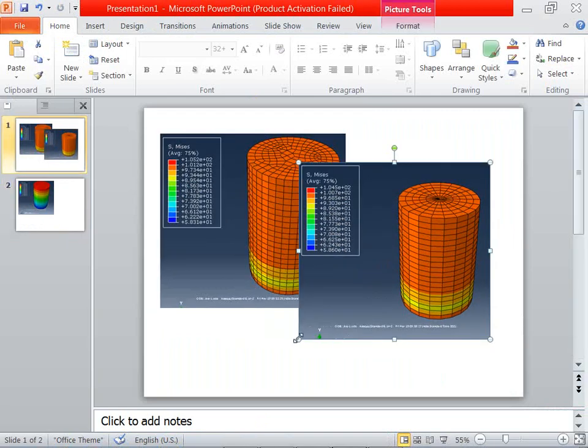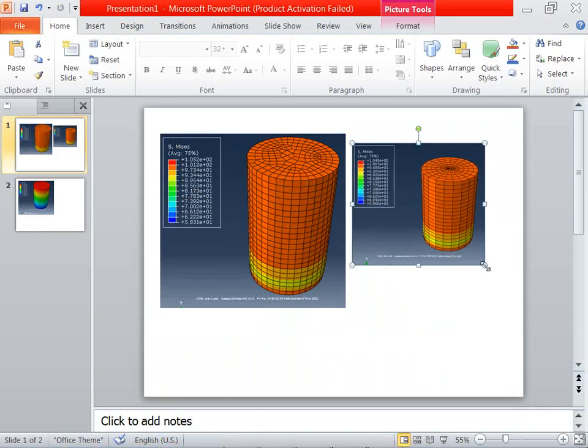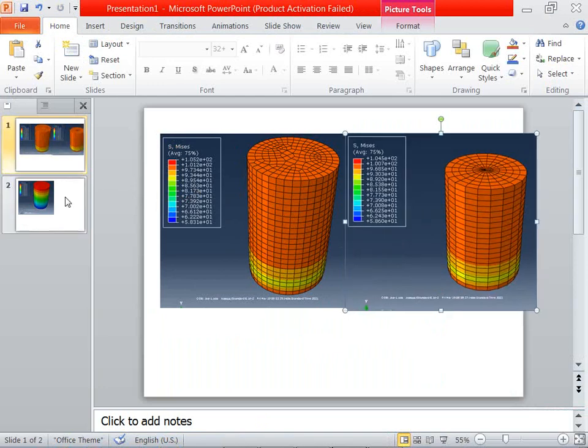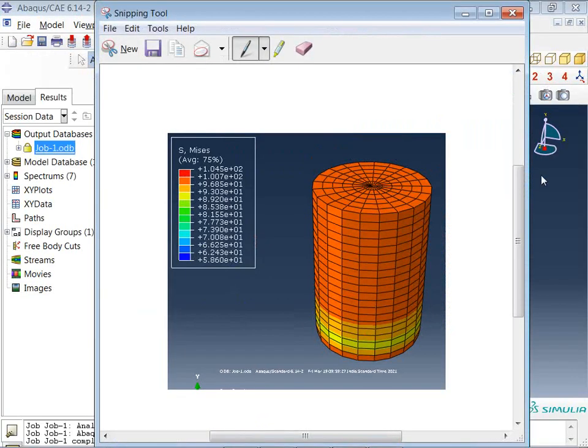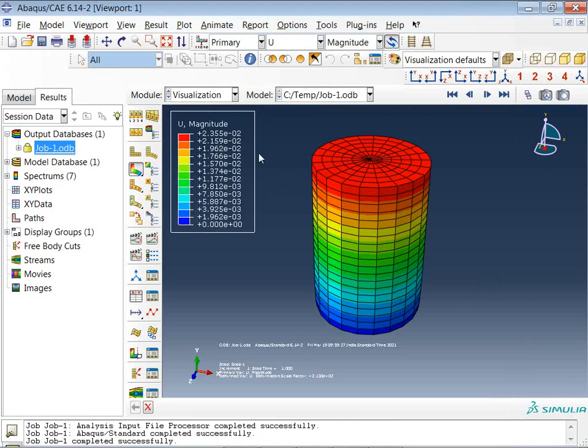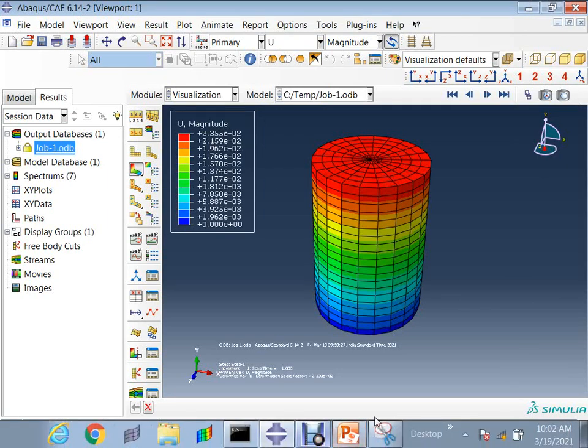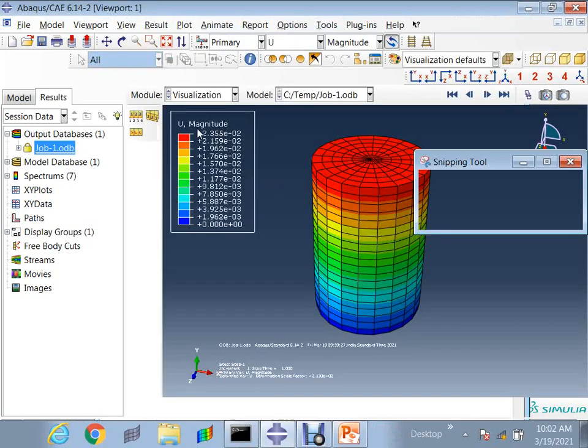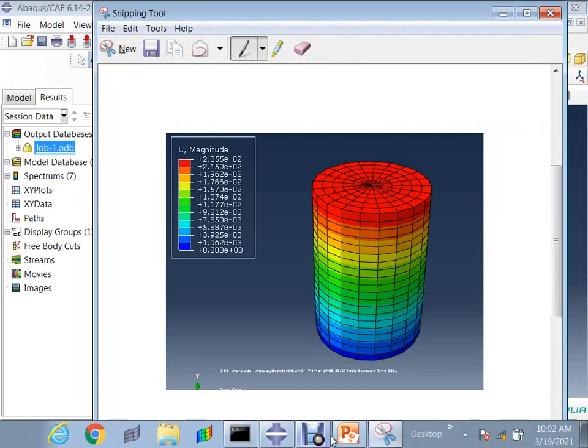Now you can see the option is to take an axisymmetric axis there and model your model at one side of the axis. If you are modeling the entire section, you need to create the axis at the left or right of it on your own. You need to generate the axis for the rotation. So that is very important to create this.